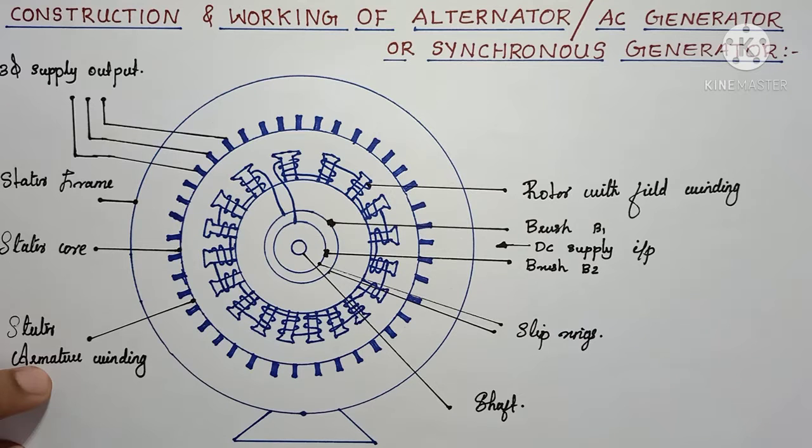We know that for the production of electrical power in rotating machines, there are three essential things. There must be a field system and there must be an armature winding system. If relative motion between the field windings and armature occurs, then we will get electrical power. For DC generators, we kept the field system stationary and the armature system as the rotating part.